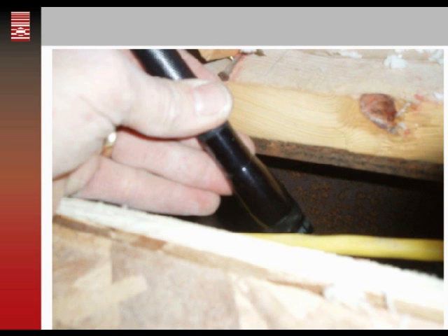And so even if we did a perfect job of sealing all of the bypasses in the units, if we didn't deal with this detail, then we would have problems with air getting up into the melting snow on the roof at this location. And this is about 6 inches wide. So you'd have a strip 6 inches wide where it's melting snow. So that would need to be dealt with also.